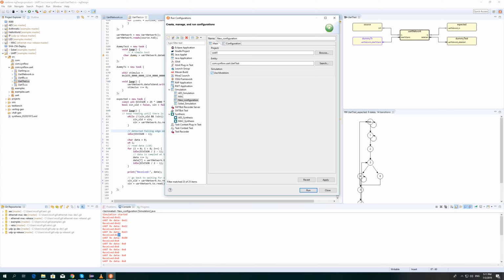So I will not compile and run the CX code, I will compile and run the generated Verilog. So what's happening when I click on Run? The Synflow SDK will compile the CX code, generate the Verilog, and then it will run ModelSim using that generated Verilog. So let's try that.